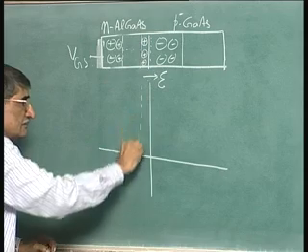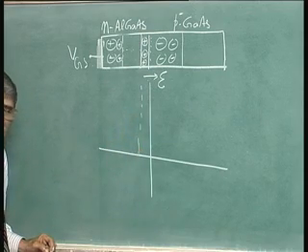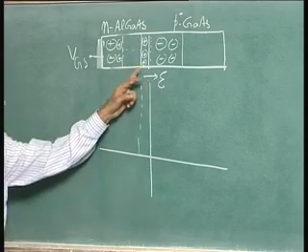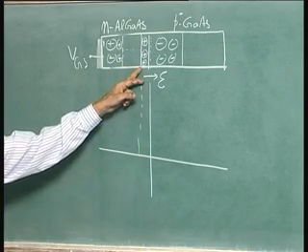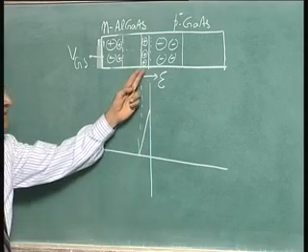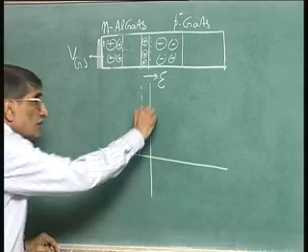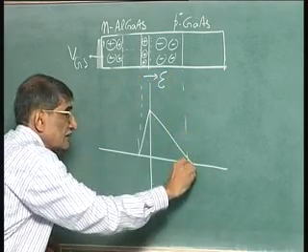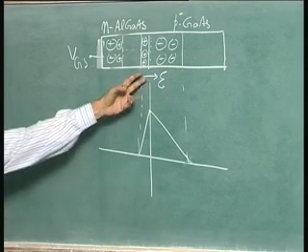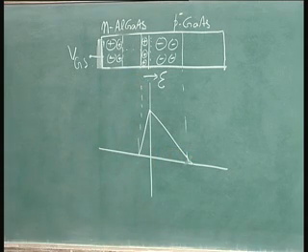Over here, the electric field is 0 here. Okay. So, the electric field is like this, steeply going up because it is heavily doped, and from there onwards falling down like this. That is the electric field distribution in the p-n junction, all of us know it.